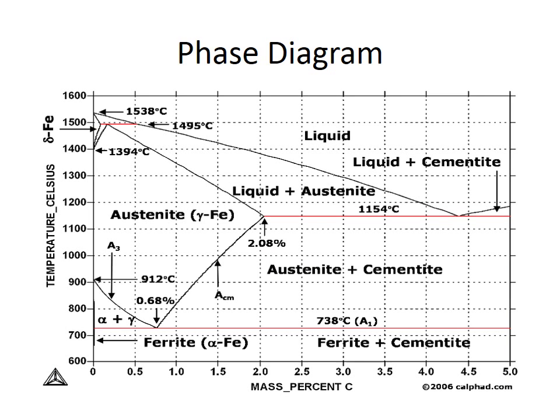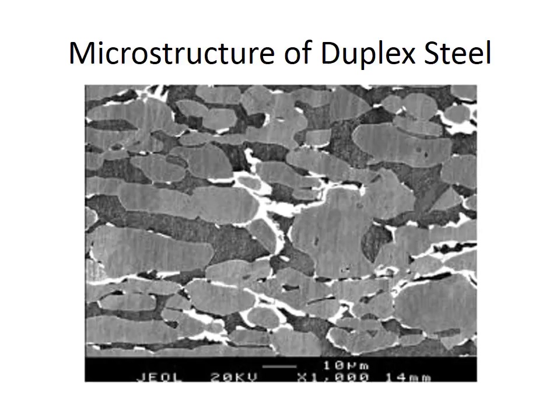Duplex stainless steels have a mixed microstructure of austenite and ferrite. The aim is usually to produce a 50-50 mix, although in commercial alloys the ratio may be 40-60. Adding chromium allows ferrite and austenite to create a steel alloy that can be used in the evaporation phase. With these superior characteristics, duplex steel can be used in desalination plants to produce a thinner evaporation shell wall that also has higher resistance to corrosion and erosion, which will lead to more efficient evaporation